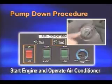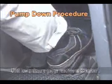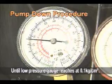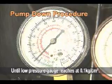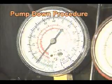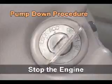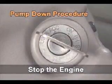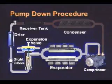Start the engine and operate the air conditioner. And then push the accelerator pedal until the low pressure gauge reaches 0.1 kilogram per square centimeter. As soon as it reaches 0.1 kilogram per square centimeter, you should stop the engine. In this condition, no refrigerant is in the low pressure line.